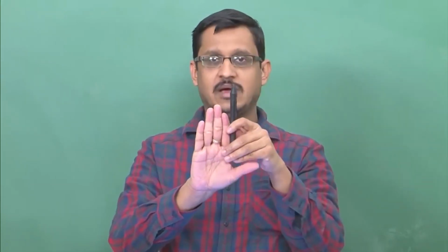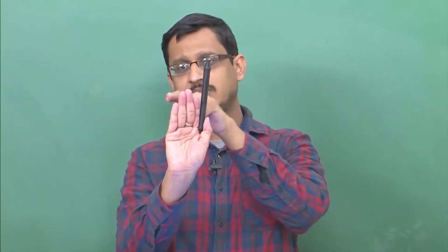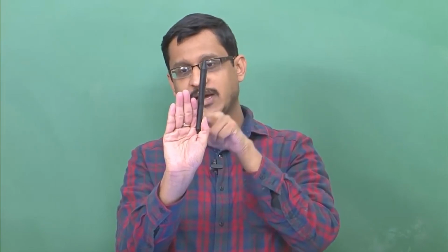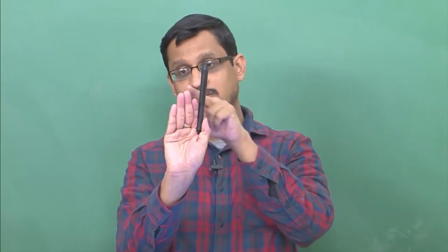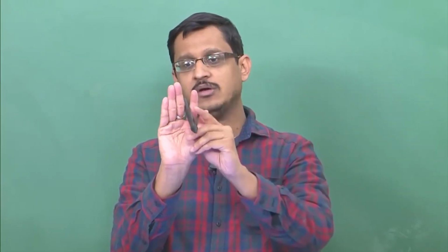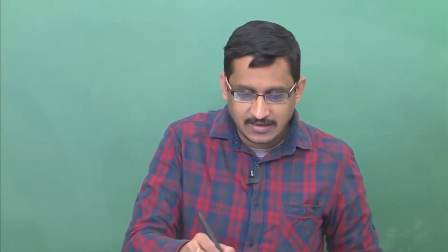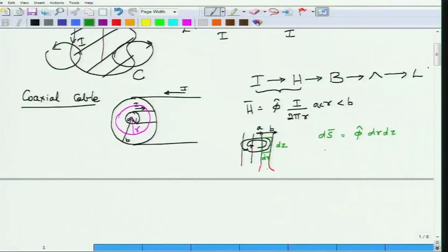So you have to imagine, I am not properly showing this one, but you have to imagine that there is an inner conductor and then there is an outer conductor over here, and I am considering the circuit between these points. Okay. So in this region there will be a magnetic field, and the magnetic fields are all going around phi direction, right. So for this conductor the magnetic field lines are all curling around, and then if you cut open that coaxial cable, you will see the magnetic field in this region, so let me redraw that region for you.